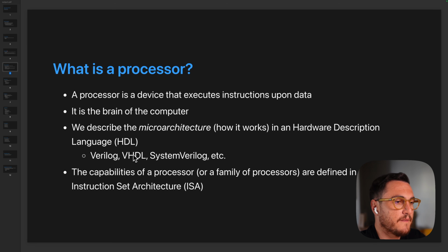It's a document that you can have for a processor or a family of processors, and it basically describes the instructions that the processor can execute, how the registers, which are the internal storage facility of the processor, are organized, and how to move data around those registers and in and out of them. So how the processor interfaces with memory, and if there are special purpose registers inside the processor. It basically details everything there is to know about our design.